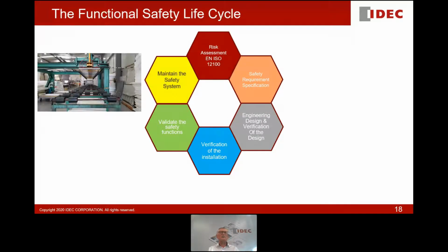Maintenance. I can't stress enough how important it is to maintain the machine and check the integrity of the safety function, not just the fact that the machine stops. Make a regular review, take a look at the safety control system, see whether or not it's still fit for purpose, identify whether or not that safety function can be improved in any way. It's a cyclical process and one which you have to address in a reasonable period of time.